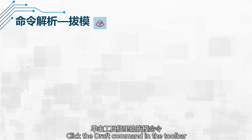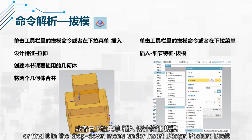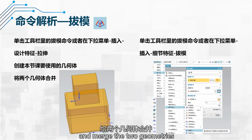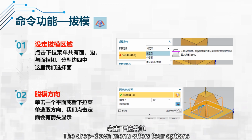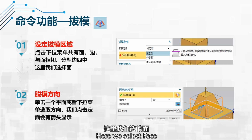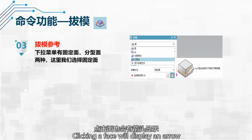Click the Draft command in the toolbar or find it in the drop-down menu under Insert, Design Feature, Draft to create the geometry we will use in this lesson and merge the two geometries. In the Draft dialog box, the top section refers to the draft region. The drop-down menu offers options: face, edge with face tangency, and parting surface. Here, we select face. The second section is pull direction. Click a plane or use the drop-down menu to select the direction. Clicking a face will display an arrow.